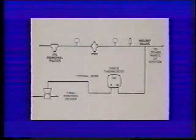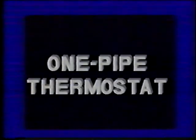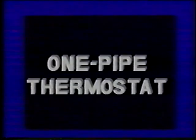This example of a typical single pressure system will illustrate the piping needed. A single pressure reducing valve or pressure regulator is used to provide a constant pressure to the rest of the system, represented here by our typical zone thermostat and control device. Main air is distributed throughout the building to our typical zones. The 1-pipe thermostat uses a single air line from a thermostat to the final control device or actuator.